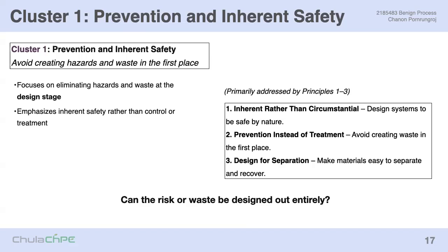These are, for example, two distinct processes, and as chemical engineers we have to design the process that minimizes separation. Often separation is costly. For example, if you make bioethanol from sugar, the process of distillation probably takes up more than 80% of the whole energy required for the whole process to make 99.5% ethanol, right? So separation is an energy intensive process. So we want to minimize it as much as possible.